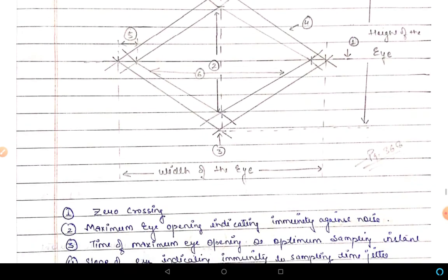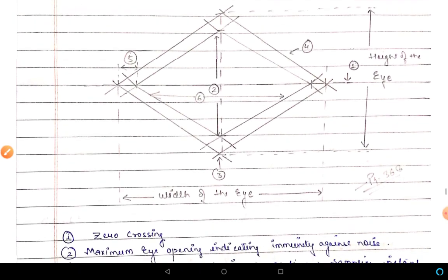If you see this region, we know that levels are crossing or zero crossing is happening, but where exactly the zero crossing is happening is not clear because of this width. This is a jitter which is called level crossing jitter, and this causes an error and it should be as small as possible.